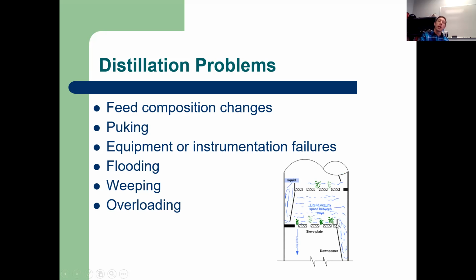that means that vapor can't rise up through the column because there's just so much liquid coming down, liquids going in between all the trays, liquids everywhere. We can't get that vapor to rise up, which means eventually that vapor is going to get carried down with the liquid and just cause more of a problem.